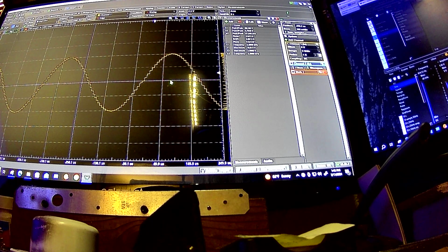So I could take this thing to 122 millivolts and still have it look the same with a 12-bit DAC. So I can make this signal a lot smaller, whereas if I was pressing my DAC to the limits, I couldn't.